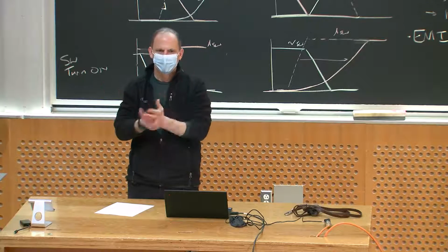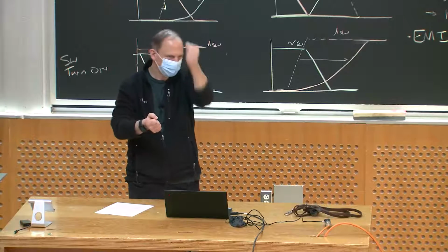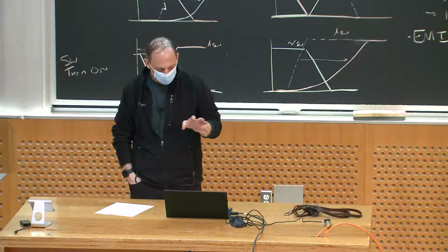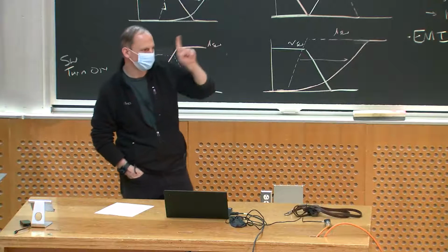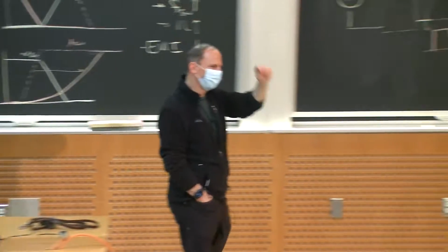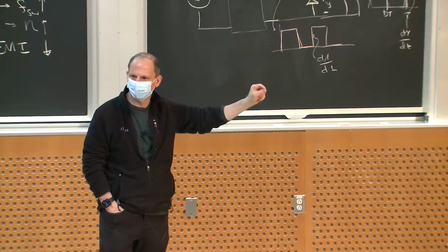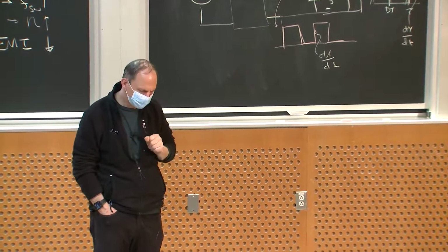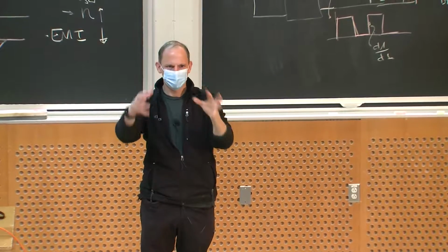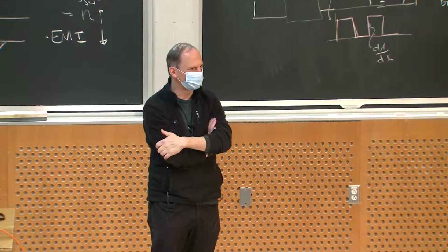You can't just generate switching angles at your command, because everything's governed by what the ripple current in that resonant inductor is doing, right? So this is nice that it lets you generate a low frequency component plus high frequency into an output and get filtered and get what you want, but it's very constrained in how you have to operate it. It's in that first category of converters I talked about.